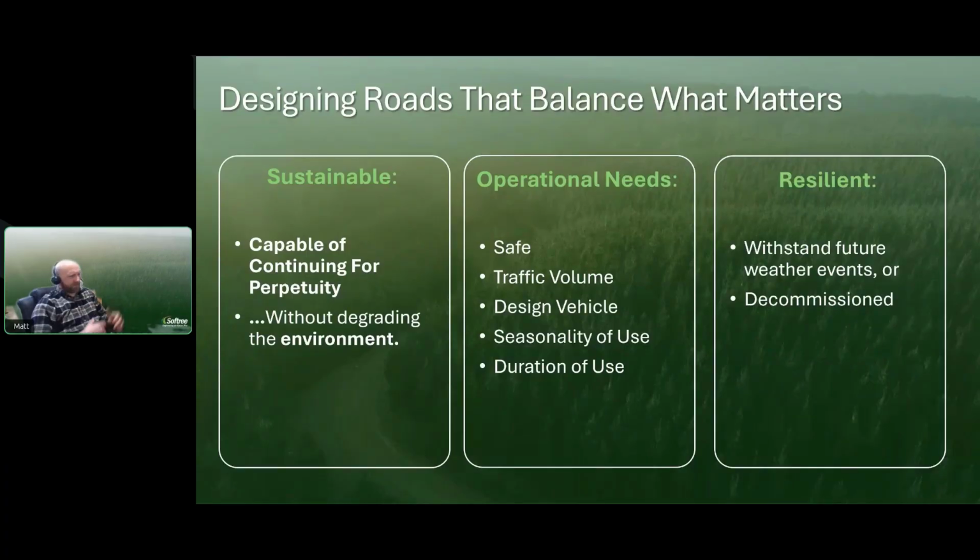So coming back to that climate tie that we had mentioned previously, if it's a location where historically there was a lot of reliance on winter roads, maybe our winter conditions are less reliable in the future, and it makes sense to hedge our bets and build more three-season roads rather than just relying on these long usable winter roads. And then there's duration of use. Sometimes we aren't really building roads to be there forever, and that's an important consideration, but you'll want to balance that as you're making decisions.